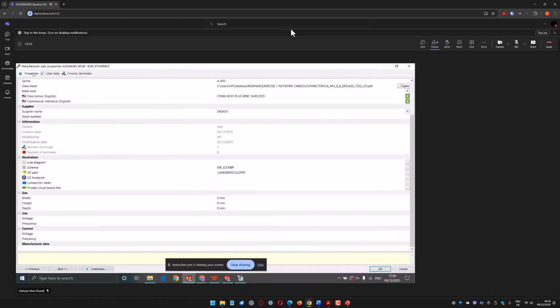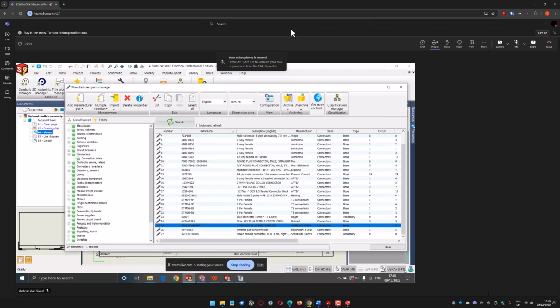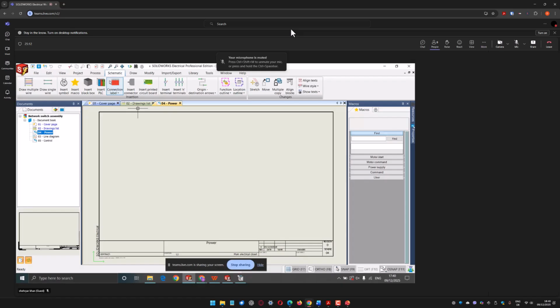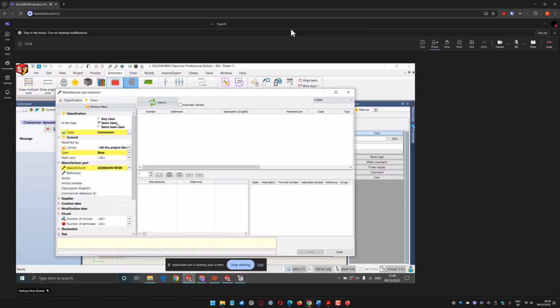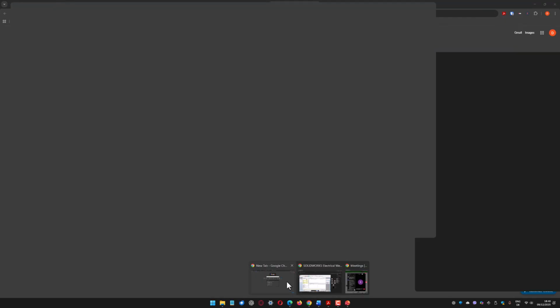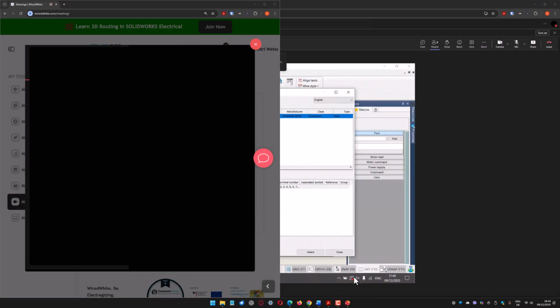And then further on, once all this is set up, we have cleared a big major step here, and I will add this connector. This is added to my library here. So now from the schematics page, I'll insert my connector, which I have already set up. I'll search for my connector from here, and we can look into different classes. These are the filters which we can use. And then definitely I'll select RJ45 and add it to my schematic with its terminals already being defined.